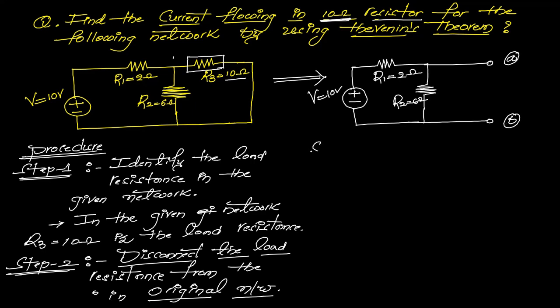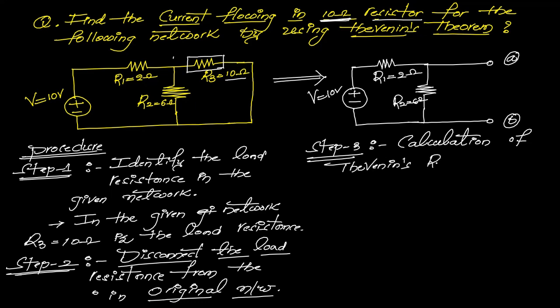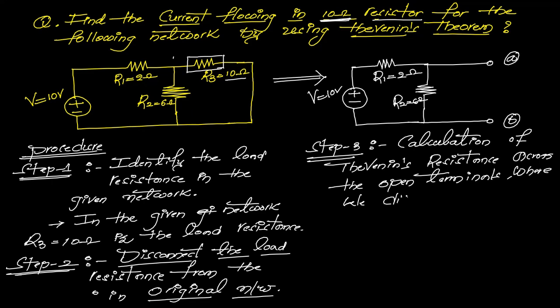Now step number 3 is calculation of Thevenin resistance across the open terminals where we disconnected the load resistance.